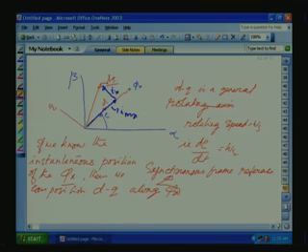So, if we can find our dynamic equations with respect to a synchronous rotating reference frame with dq placed along psi r, then those dynamic voltage and current conditions are the ones useful for our vector control applications.